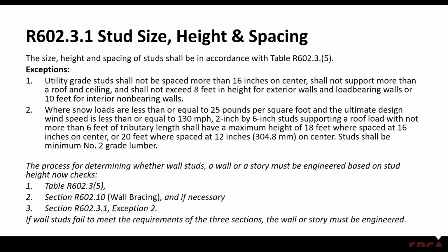A couple things here regarding studs. The building code in chapter R802.3.1 lists the stud size, height, and spacing. You're allowed to use utility grade studs that are not spaced more than 16 on center. They shall not support more than a roof or ceiling and shall not exceed 8 feet in height for exterior walls and load-bearing walls, or 10 feet for interior non-bearing walls.